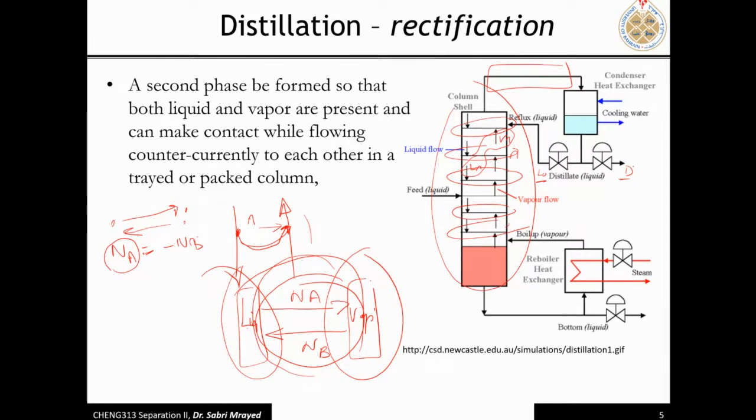In the distillation column, which works based on tray columns, we calculate how many trays we need to achieve the required separation in this process. But for both designs, the idea is based on distillation, which is based on the difference in the boiling point and on the equilibrium constant or the distribution coefficient between these two components.